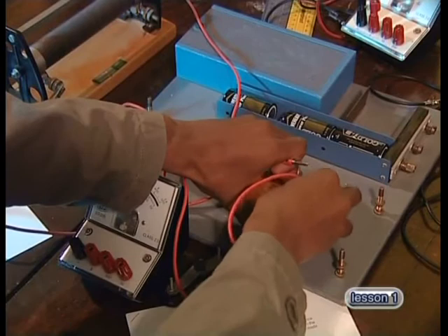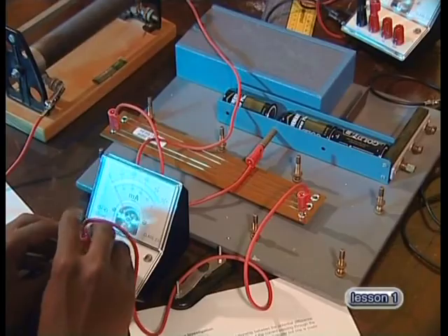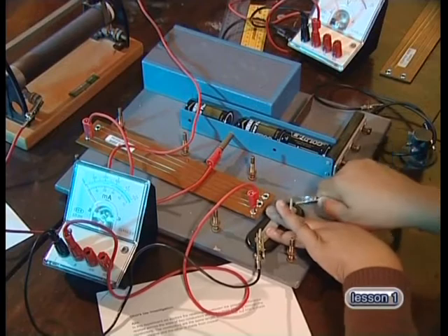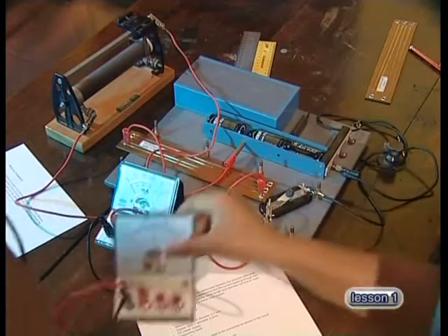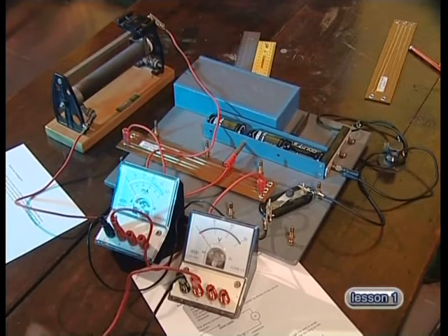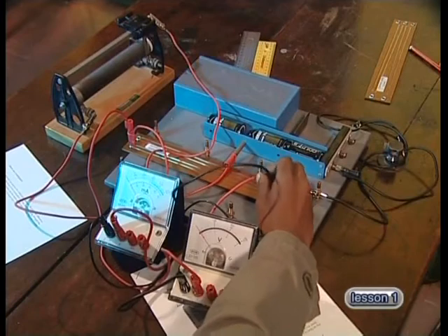Remember to put this connecting lead into the red positive terminal of the ammeter because we started from the positive terminal of the battery. Conventional current direction is from the positive terminal to the negative terminal. Good thinking. Next is the switch. Now we need to connect the voltmeter in parallel across the wire. The red terminal needs to be connected to the end of the wire next to the rheostat, and the black terminal must be connected to the end closest to the negative terminal of the battery.